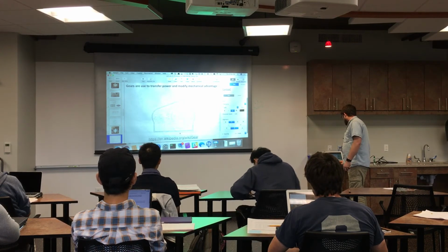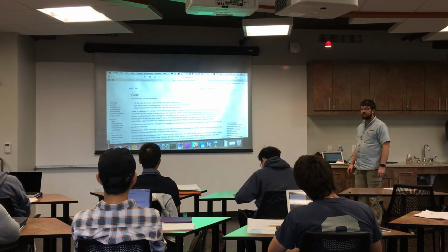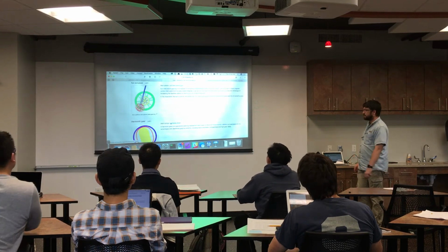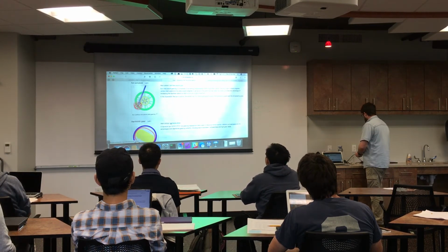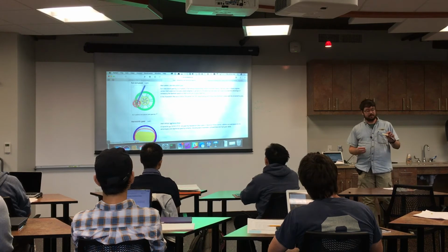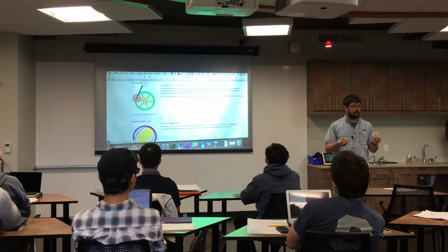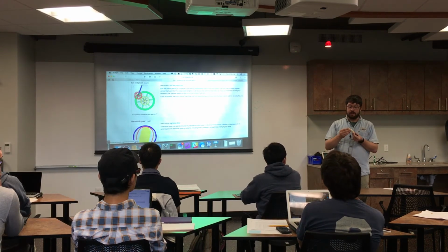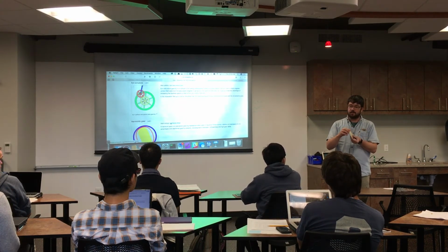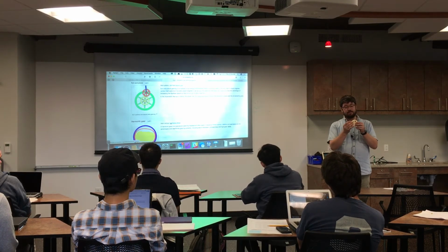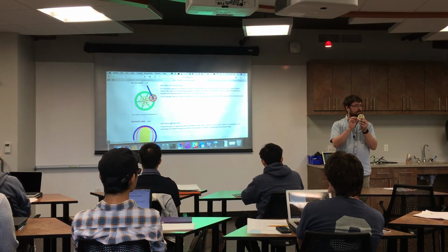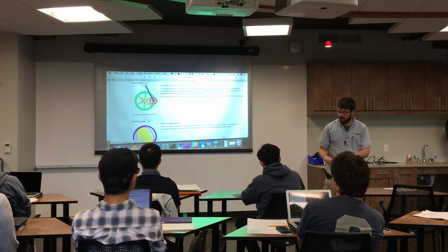Somebody put a lot of time into the Wikipedia page on gears and made really nice animations, better than I can make. I'm going to pass around a couple of gears. These are actually 3D printed, and they're used in my 3D printer. They've worked for a very long time. These are herringbone gears. They've got these chevron-shaped teeth, and they mesh very nicely. They're used in this case for reduction. So the motor turns here, and it moves this big gear a very little amount to precisely control the positioning on the 3D printer. But I'll send those around.